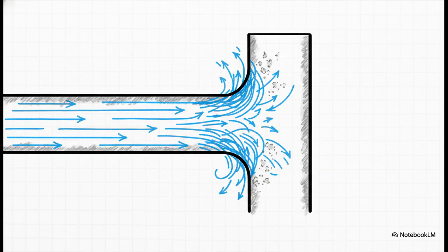Here's a perfect real-world example. In any piping system, it's almost never the long, straight runs that fail first. Nope, it's the elbows and the T's. Why? Because as the fluid turns that corner, it gets turbulent, and that turbulence can literally strip away that protective passive film, exposing fresh metal to be eaten away. A simple change in direction creates a corrosion hotspot.